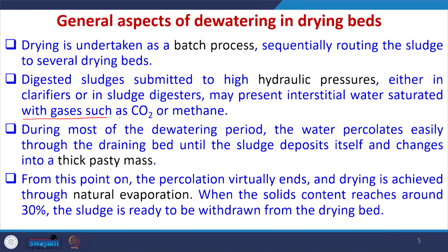Digested sludges submitted to high hydraulic pressure either in clarifiers or in sludge digesters may present interstitial water saturated with gases such as CO2 or methane. So, it is possible during most of the dewatering period the water percolates easily through the draining bed until the sludge deposits itself and changes into a thick pasty mass. So, it is there. From that point on the percolation virtually ends and the drying is achieved through natural evaporation.